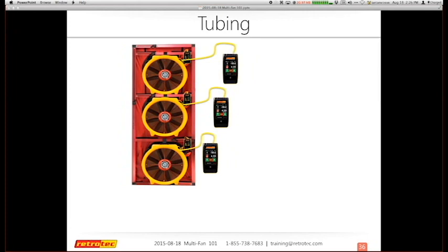Always have your software set on individual control, and then rewire your control signals so that the fans get the signal from fan number 1. Because once you disconnect the signal from the gauge, and you take the signal from fan number 1 and send it to fan number 2, it doesn't matter what gauge number 2 says. It's going to follow along.